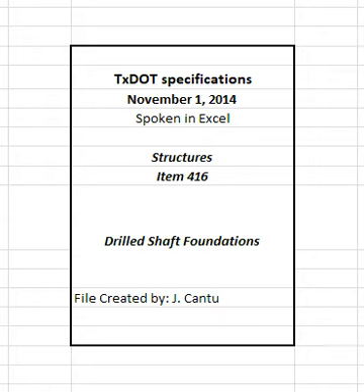3. Construction. Submit drilled shaft installation plan for review no later than 1 month before drilled shaft construction. Include the following in the plan. Name and experience record of the drilled shaft superintendent who will be in charge of drilled shaft operations for this project. List of proposed equipment to be used, including cranes, drills, augers, baling buckets, final cleaning equipment, desanding equipment, slurry pumps, core sampling equipment, tremies or concrete pumps, casing, etc.